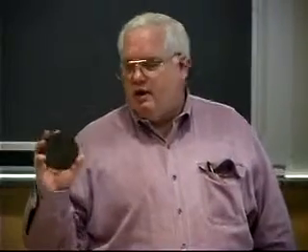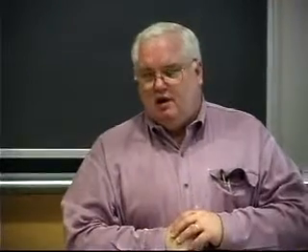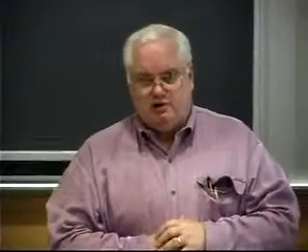But we can do plasma cutting. Or actually, this was laser cut, and I'll pass it around tomorrow or Monday. This is stainless steel, about a half inch thick. It's plasma cut. Plasma cutting, I'll describe next time, is basically a form of a jet burner using an electric arc, where you ignite the arc in a closed chamber and shoot out a high velocity jet of very hot 10,000, 20,000 degree gas, which just melts the surface.